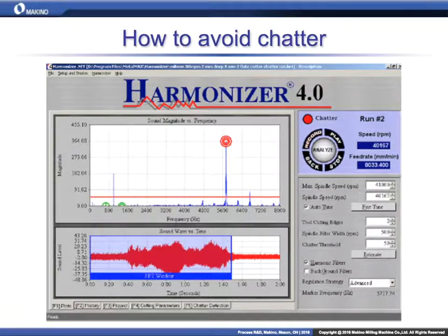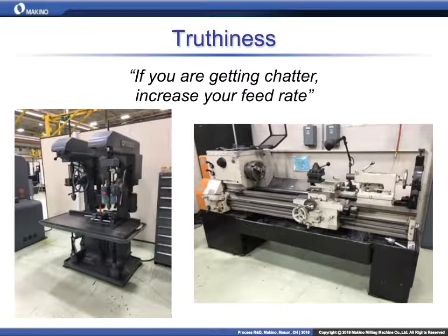So the first one, and this was one of the first things I heard as an applications engineer, is if you're getting chatter, increase your feed rate. How does that one hit you? That's not an all-encompassing statement. You need more information to be able to say that. Maybe jumping the gun on that. I would gather more information before I told somebody. You can't use it as a blanket statement that applies to every situation.